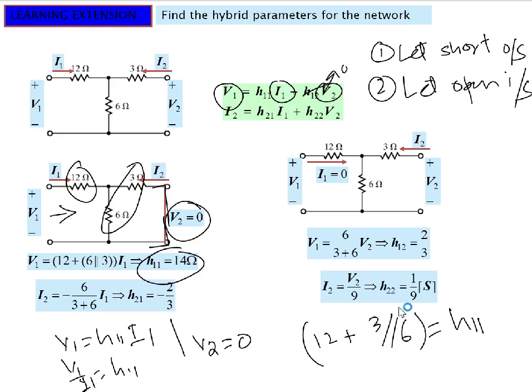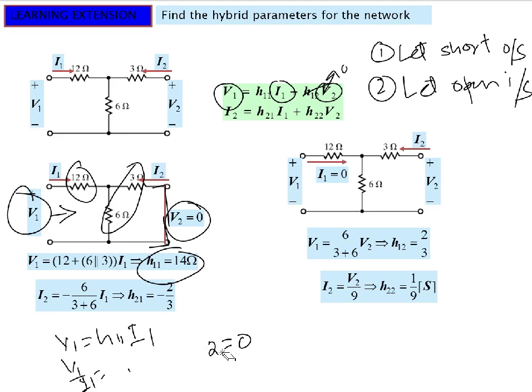You can also say that we want to calculate the voltage on the primary side. This is the second method. The first one is this one that we have calculated the parallel combination of these two resistances and added this third resistance here. In the second method we use the V equals IR method. So V1 is equal to I1 and R1.